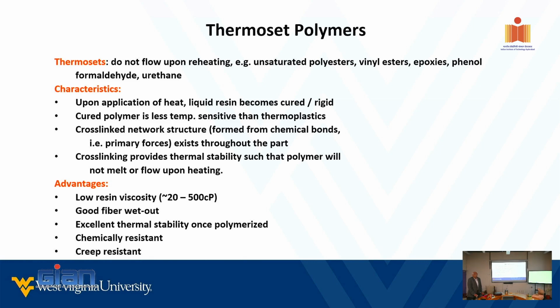That made it so difficult to process a product. I couldn't pull the product, I couldn't spread the resin, so I had a problem. Now that we have low viscosity resins, this is where you tweak a resin. You saw my molecular structure, so we tweak that structure to make it a low viscosity resin.